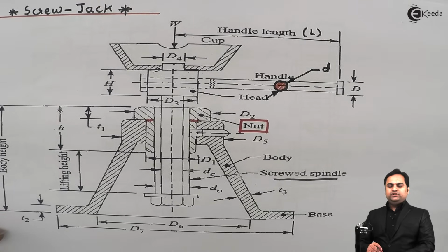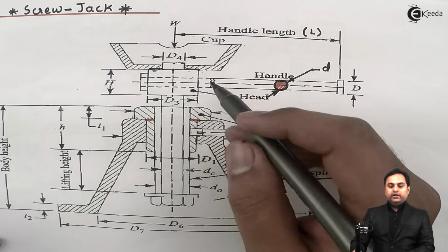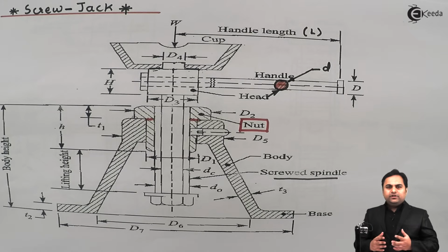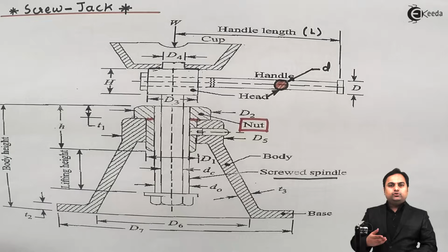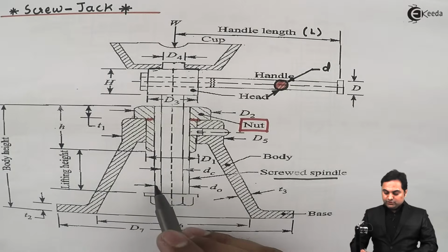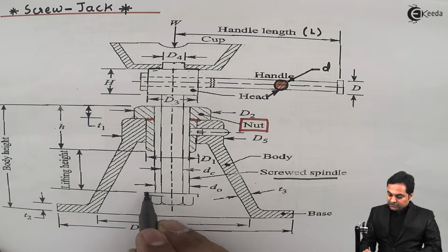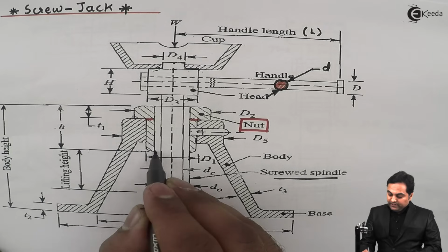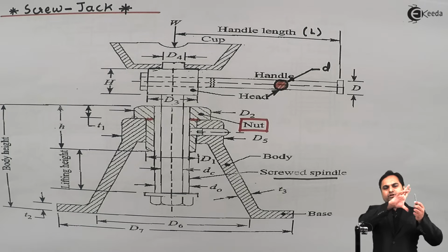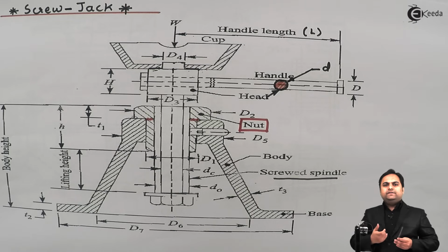Now the last step, which is there in case of the design of screw jack, now we will write the value of load at which this screw will try to buckle, which is called the critical load. See, what is the meaning of buckle is that when the screw is lifted to its topmost position, that is, about this entire lifting height. Here in the diagram we can see the screw jack in the bottommost position. Now when it is in the topmost position, this end of the nut here will be attached here, and this screw would be entirely lifted. So when it is completely lifted and when the load is applied over the screw, then it is a case of buckling. The screw will buckle in the lateral direction.